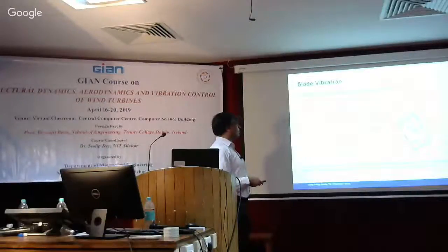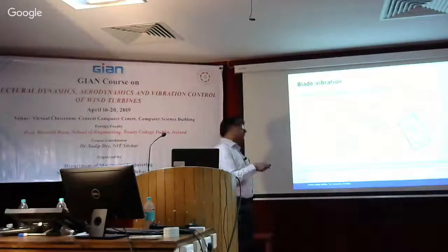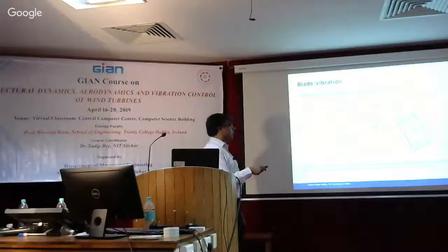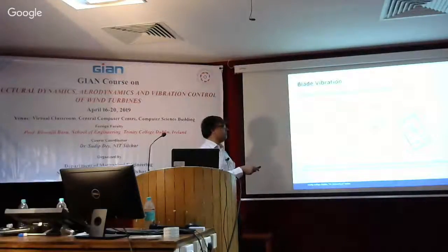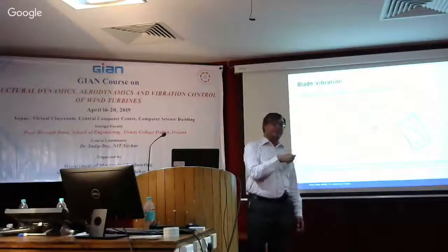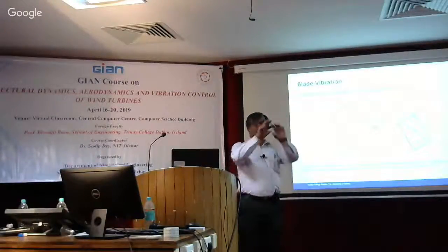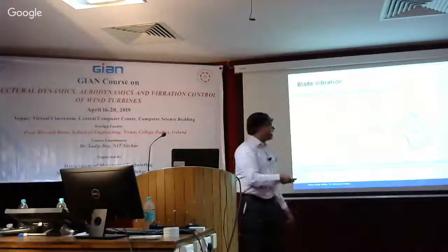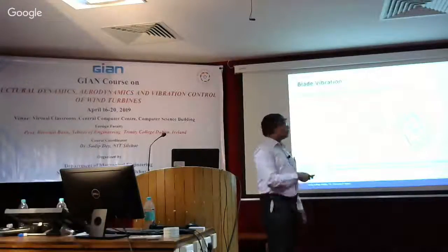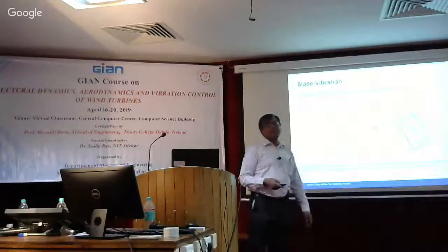This is actually a sloshing damper, so a tuned liquid damper. And here we have a tank, which is again located here. This is a paper we published in Journal of Fluids and Structures, on the fluid interaction here. We did a variational formulation, looking mainly at the fluid response, because the fluid response in this case would be far more difficult to model than the previous ones. In the previous ones, because the fluid is moving in a tube, it's very well constrained. It's always in a kind of laminar flow. But in this case, you will have liquid sloshing happening, and also you may have breaking of the waves on the surface.